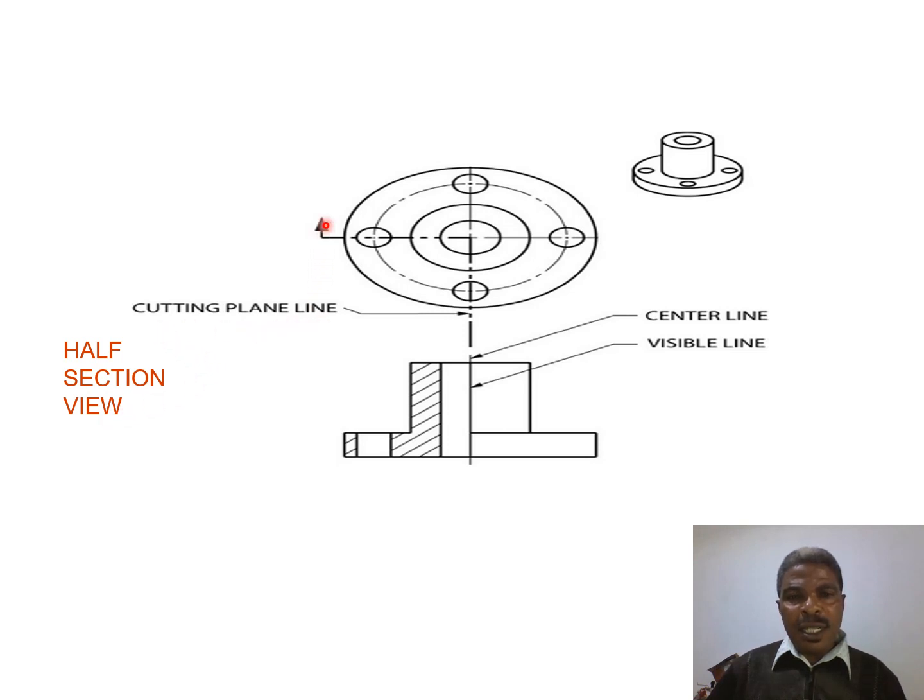Here you can see the cutting plane with an arrow on this side. So this part is like a quarter of the object. This is our object, and we have a cutting plane, just a quarter of it. We have said half will be presented. It was supposed to pass through up to this side, and that would be the full section. But being a half section, it has to go in this direction. As you can see, the result simply indicates just this part of the object.